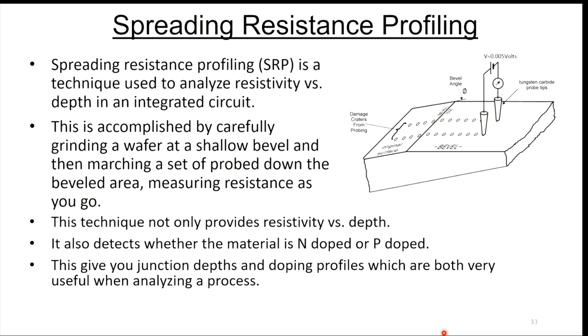Okay, if not, I'd like to talk about a completely unrelated subject, spreading resistance profiling. You may have never heard of this before. This is SRP for short, and this is a technique used to analyze resistivity versus depth in an integrated circuit.